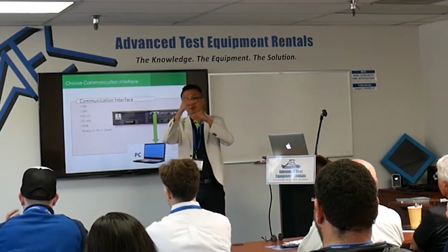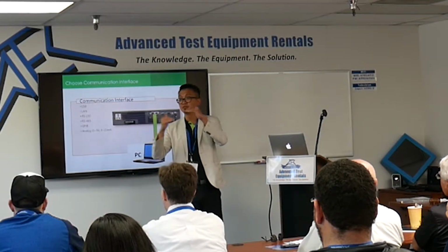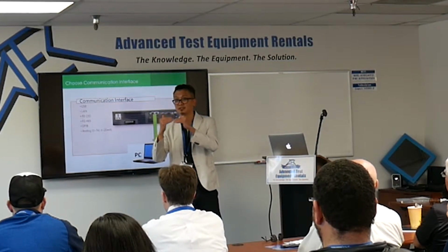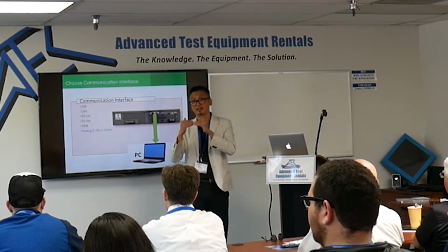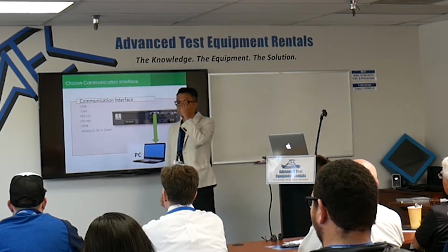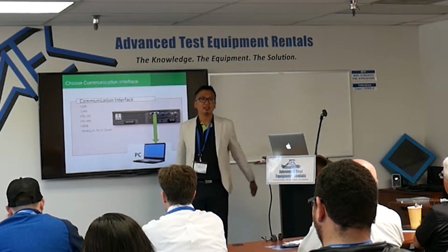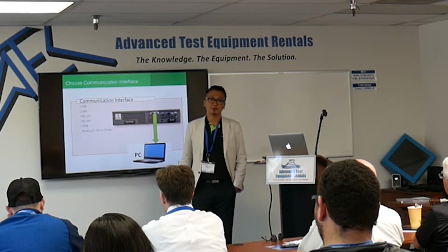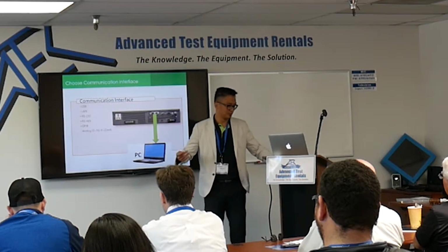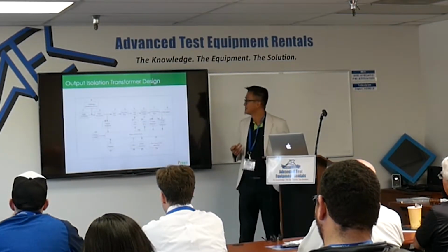But RS-485 is differential. So even over a long distance, if you use a good isolated cable, you still get a good signal. That's why on the facility side, like in the military, sometimes they like RS-485 for longer distances. So that's very different.